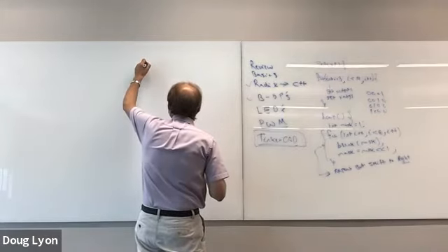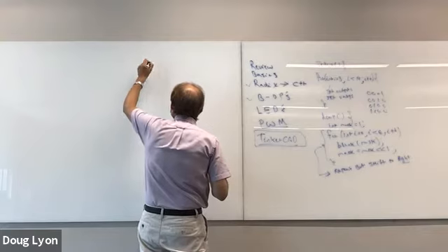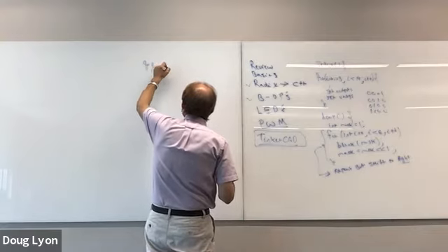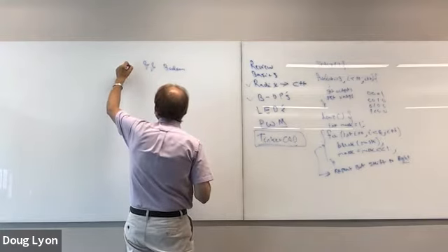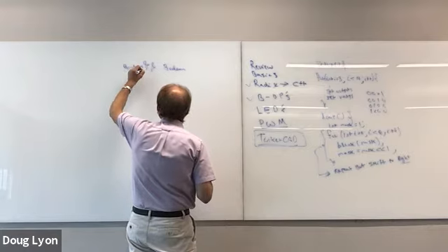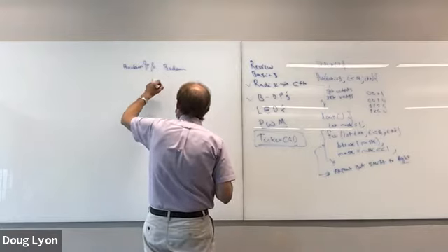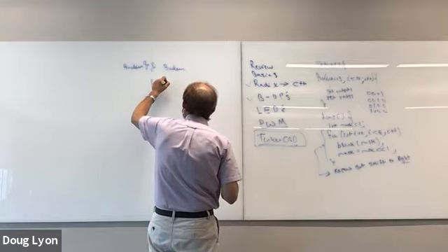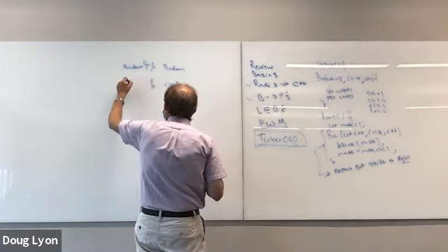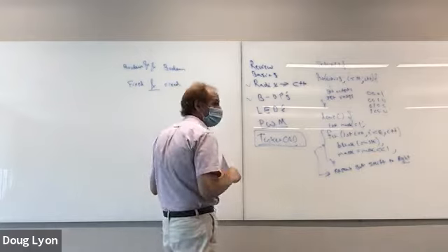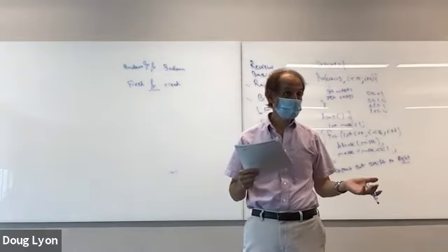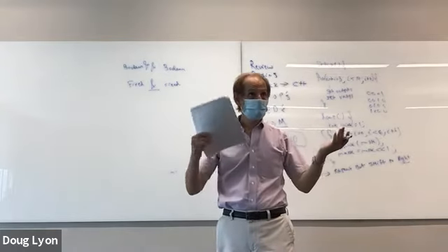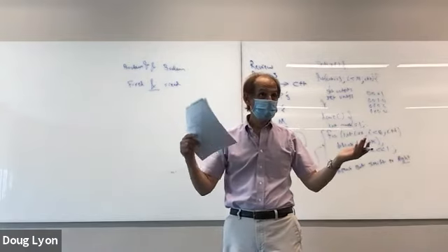So for AND, use ampersand, ampersand, and then the two types are Boolean and Boolean. But for a single ampersand, what you want is a fixed point data type, because that's doing a bitwise AND. Right? So the bitwise AND is really different from the Boolean AND. Boolean AND says true and false is equal to false. False and false is equal to false, right?